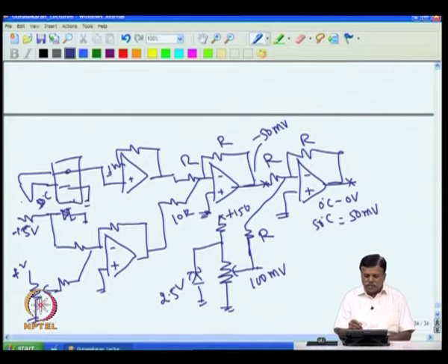So, the oven is now at 50 degree C, so I will get minus 50, and this is 100. So, the net result would be that you have a plus here more. You will get minus 50 millivolt here. If I increase this, as long as this is higher, then you will get more and more minus here.